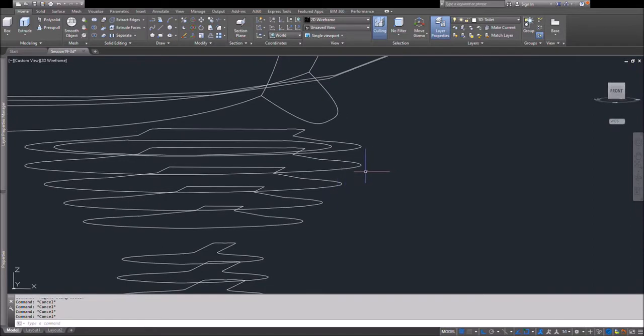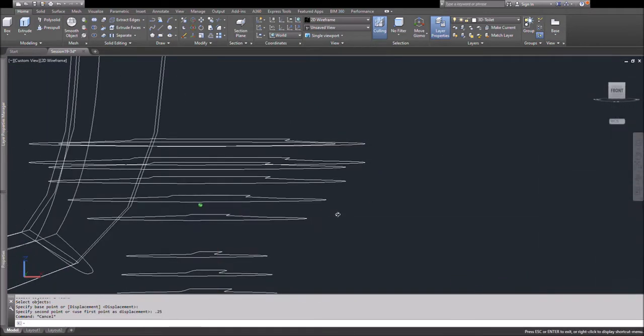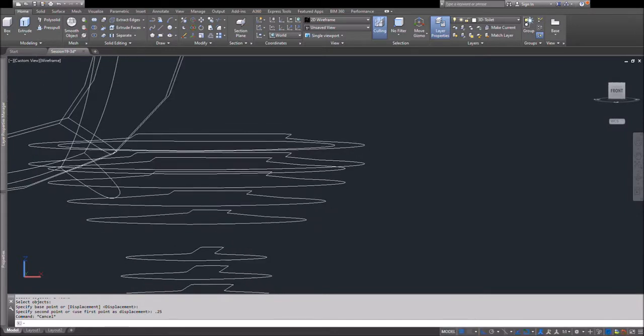So right now, all the commands I've been using so far are everything that we've talked about. I'm using P lines, right? I'm using my move command, whether it's a 3D move command or just a regular move command, and moving polylines either to the left or right, or moving them in the Z axis, right? That's all I'm doing at this point. It's really only going to be a handful of commands to be able to model this, and it's going to look a lot more complicated than it actually is.